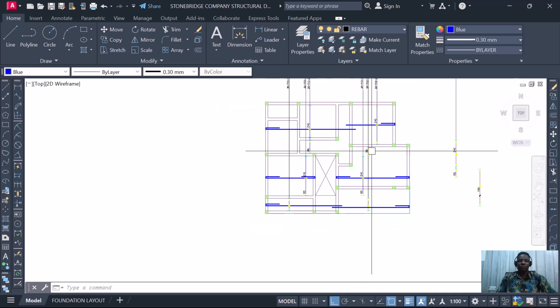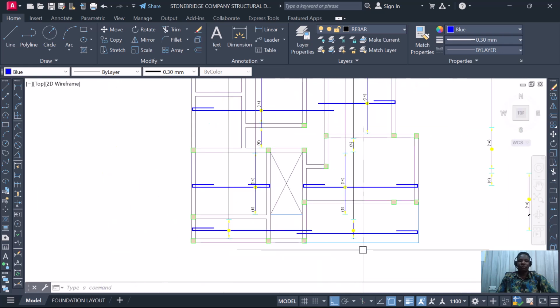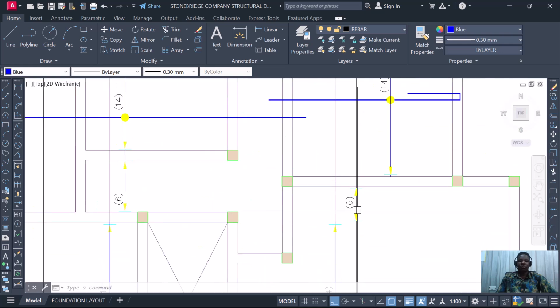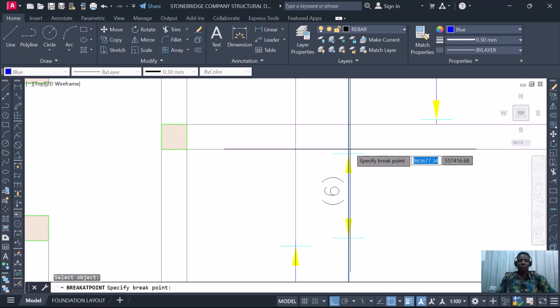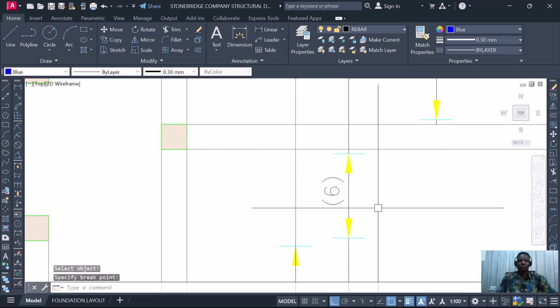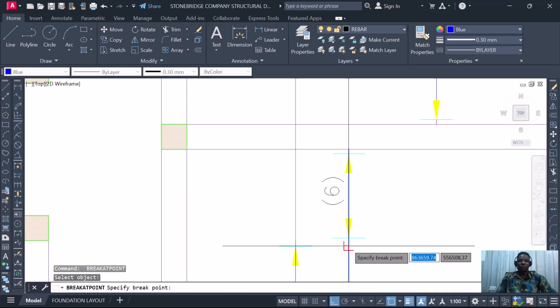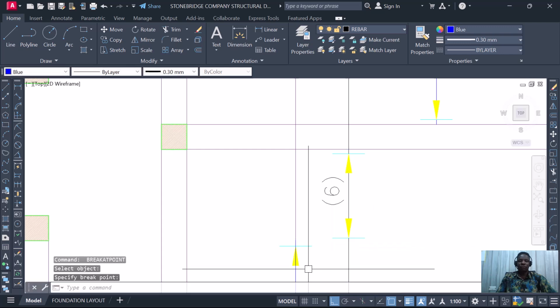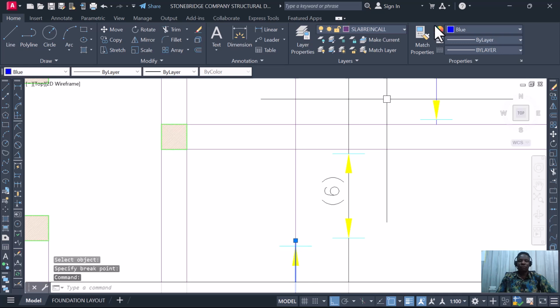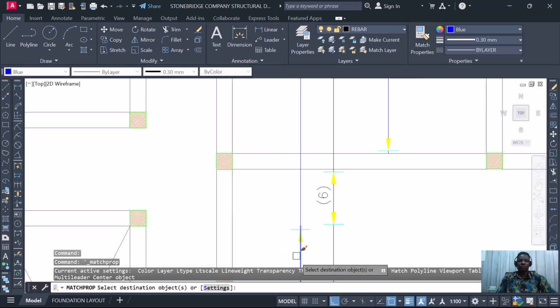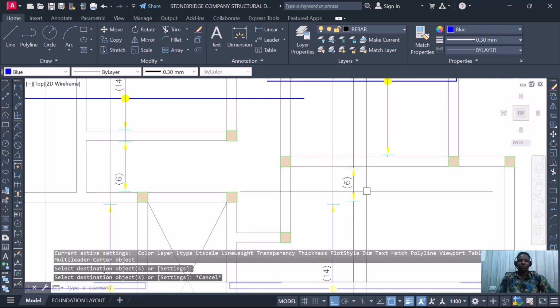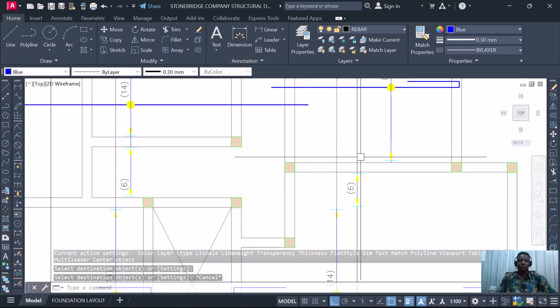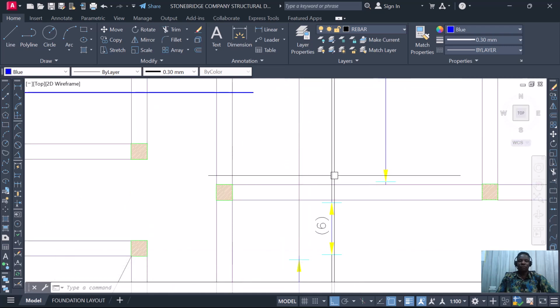So there's an extension over here, which this guy is lapping over. So there's a space over here. Okay, so we are going to say that let's use this rebar to also replace what we have here. Otherwise, we are going to copy this and paste over here to run that particular region. All right, so I just want it to run along this span and also run along this span. So what we just need to do, I have to create a break there. So click create a break. You click on break, you come at one point, you click, you repeat the same procedure by clicking enter, you click on the beam and you go to the next one and you click.